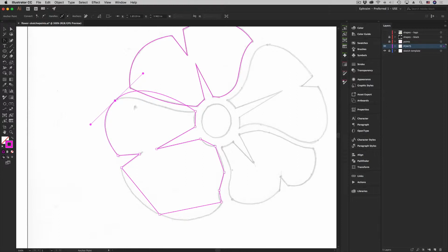And there we go. Now, in an earlier movie, I showed how this curves in. We can see this is curving in. So anytime you have a shift like that, what I like to do is set up another point. I said to use as few points as possible, but I think we're still pretty good here. So I'm going to go back to my pen tool. Also the S key on your keyboard will do a quick selection of that pen tool. I'm just going to click a point here, and then temporarily again, to activate my direct selection tool, I'm going to hold down my Command or Control key, and I'm going to drag this down.